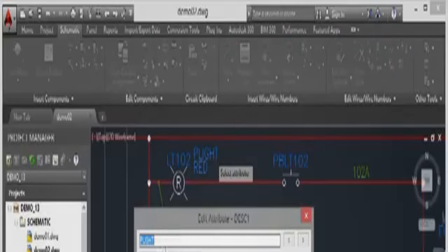It's very, very easy. Edit attribute. So all I've got to do is type in Pilot. I can pick similar text on the drawing if I want to. If I click here, it updates the last letter each time. And when I get to Z, it then goes Z1, Z2, and so on. So you can see that I can advance it character by character if I want to.